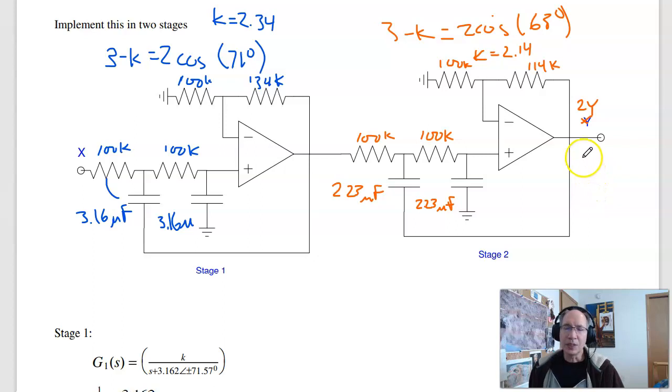One option is to reduce the gain, add a gain of a half to the circuit, or just live with it. Typically, I'm going to have some other circuitry amplifying the signal. This guy gives me a gain of 2, free of charge, so I might as well use it. And that just means the rest of the circuit needs less gain. And I can model that just by saying the output isn't y, it's 2 times y.